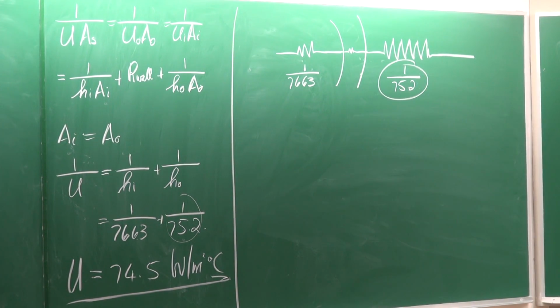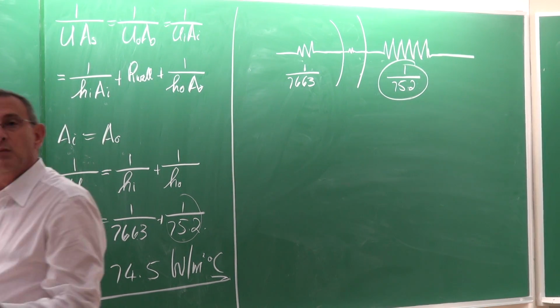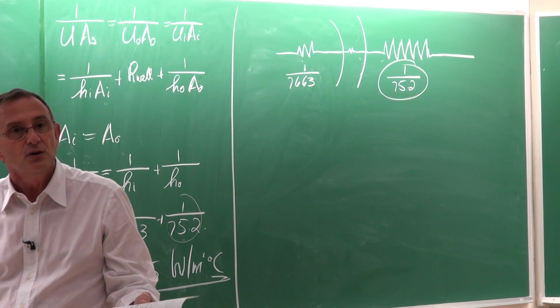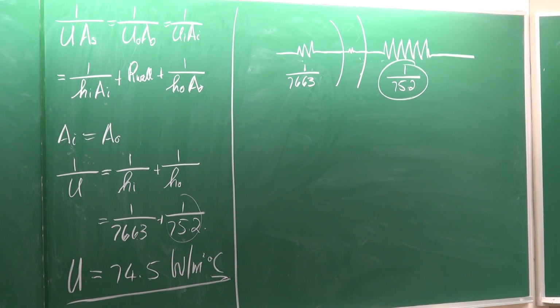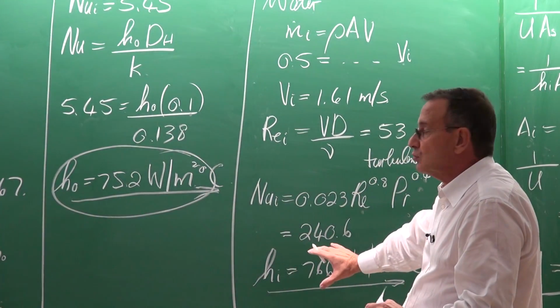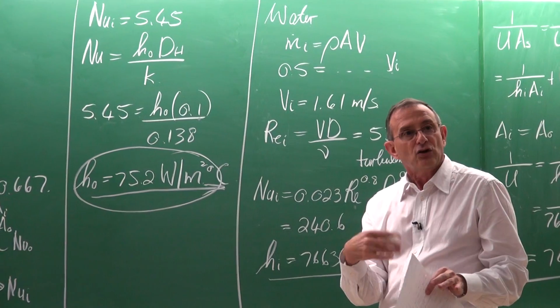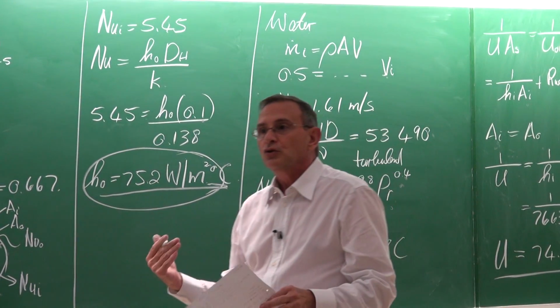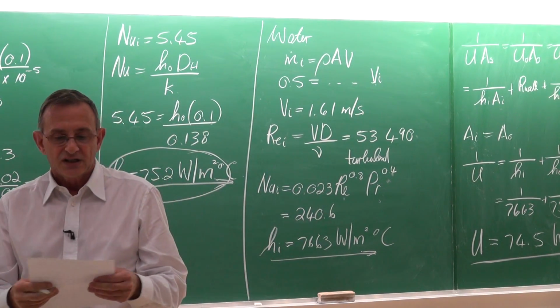So, it means that if you've done many of these heat exchanger calculations and you've developed a little bit of experience, then you can make life very easy for yourself by looking at the different resistance terms. From there, you actually have a very good idea what the overall heat transfer coefficient will be and how to correct the situation to increase the efficiency of a heat exchanger.